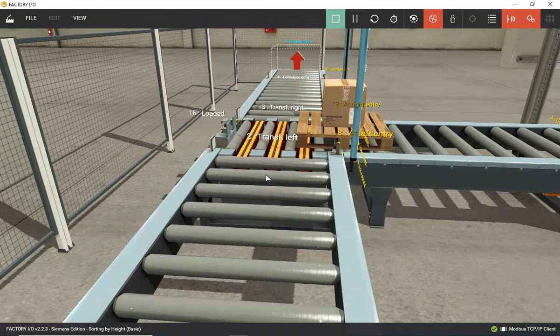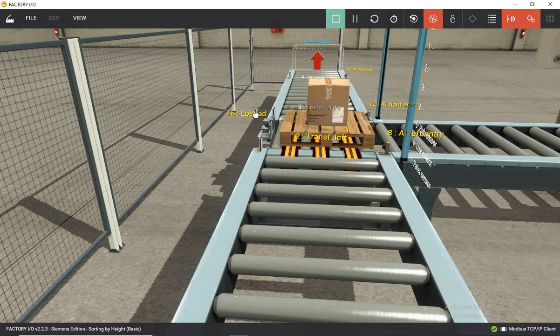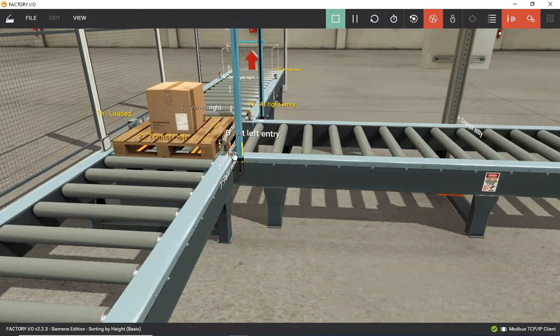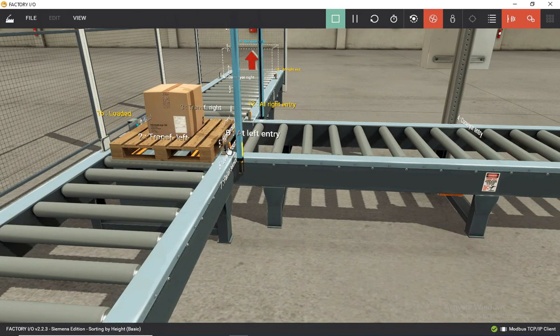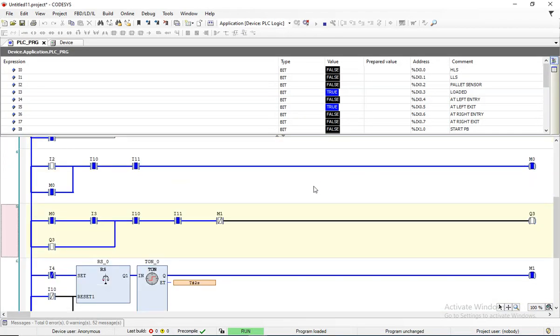Palette sensor is on. Look, when the load sensor is on, this starts to push forward and the conveyor belt is on, and then the 2 seconds there, 1, 2, it goes back, so it can't move because the 2 seconds is very short. The 2 seconds is already engaged and this has been stopped, so we just need to increase the time and then this will definitely work.